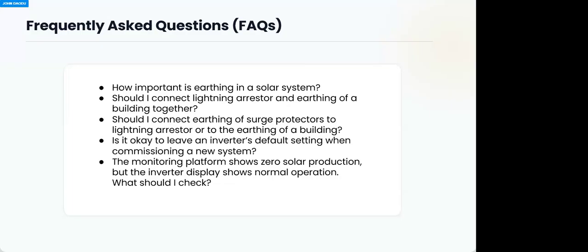It is the best because it serves as a protection for the whole system. Now, this is how it works. Unless the manufacturer of the inverter wants that, do not connect the neutral of the input to the neutral of the output, because that's what makes it common.